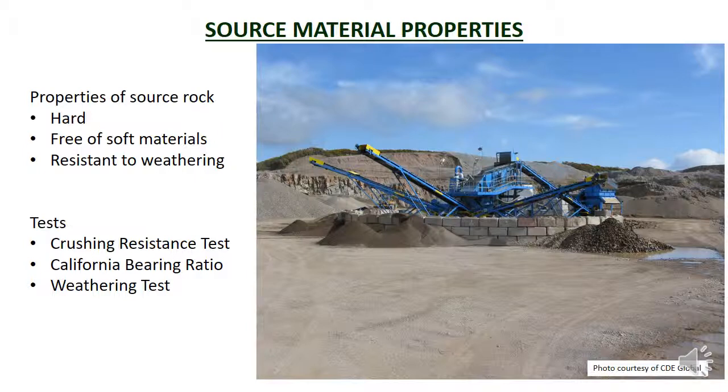This is a photo of an overseas quarry. You can see the quarry face in the background where the rock is removed from. In the foreground is a machine which crushes the rock and sorts it into different sizes using screens. The different sizes are then blended to form the BASECOURSE aggregate.